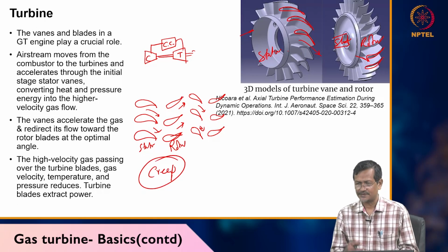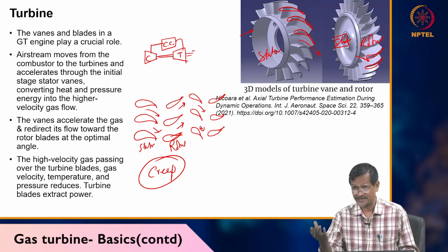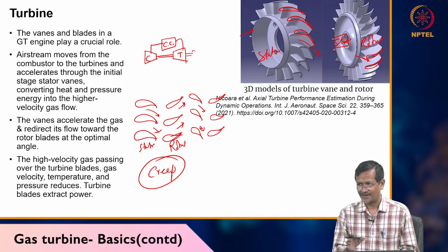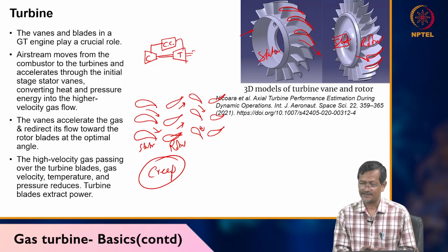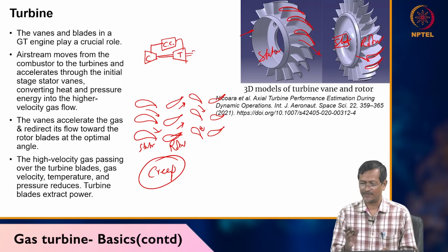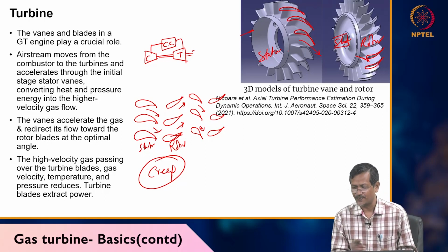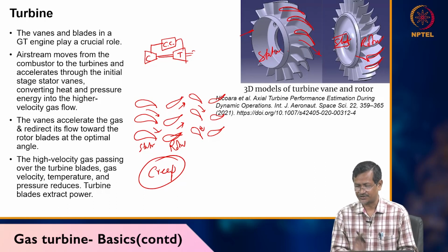Okay, so creep means that over a long time, if it is facing that high temperature, permanent deformation of the blade is possible. At high temperature, centrifugal force is there and it is harnessing energy also, so there is extra force, and again the temperature is high. In that case, the blade material can be changed permanently; its shape or size will be modified. That will be harmful for the turbine system. It may harness less energy, or it may fail continuously. It may fail because of its rotation.